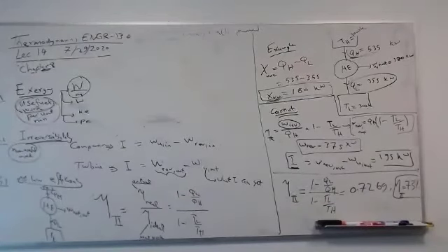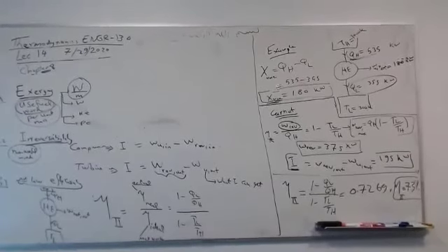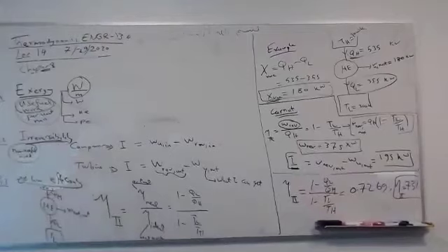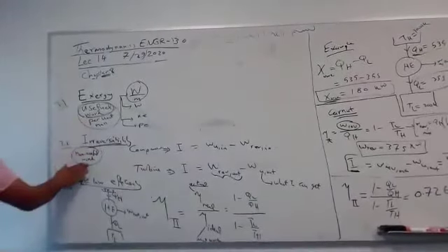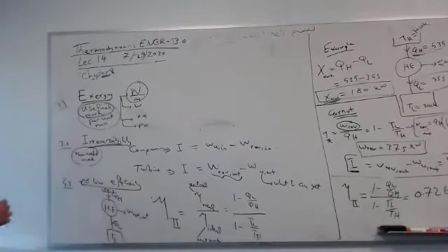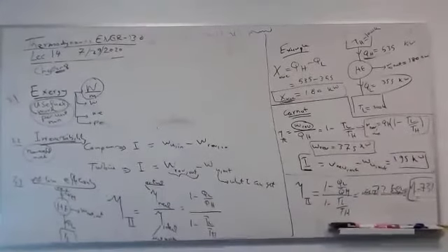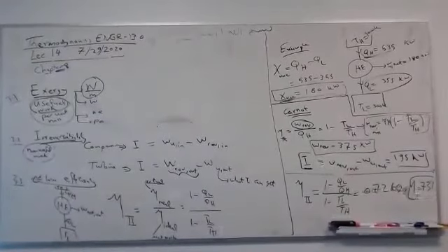I'm still going around, but I'll give you more definitions in thermodynamics. Definition means how can we say this system is good or bad? So we wish to have zero irreversibility. I wish to get the maximum useful work, 100% second law efficiency. So these three represent how bad or how good your system is. This is the last three definitions we're going to take before jumping into cycles.